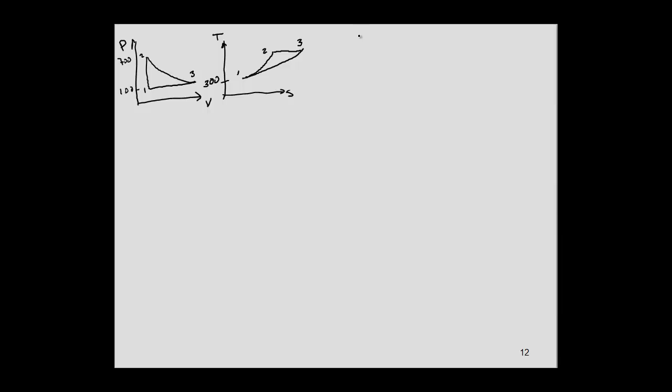So we should recognize that we have a fixed mass, and because we have a fixed mass and we have air as an ideal gas, PV over T equals, let me change this to just emphasize that this is lowercase v, it's constant, right? Because we have the same mass.